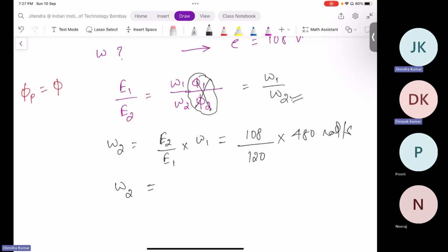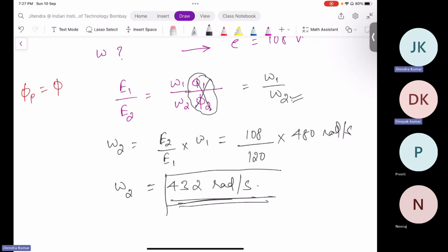432 radian per second. So now you must be able to observe what happened. As was earlier mentioned, the speed will reduce and it will be constant at that speed in the steady state. And that is the speed when your load desires 10 Newton meter of torque and you have to supply it, then your speed will be 432 rad per second. Is it fine? Any doubt?